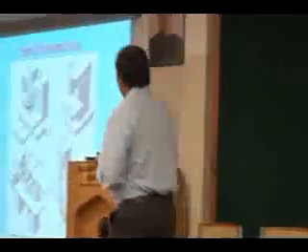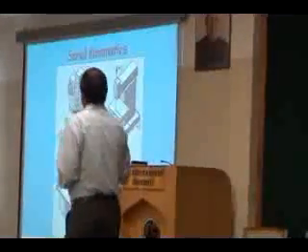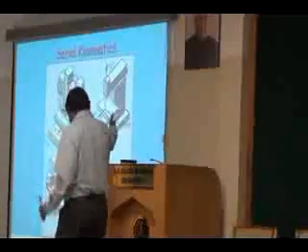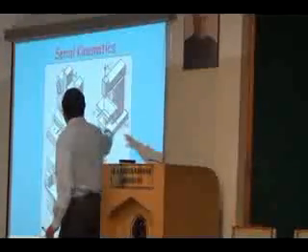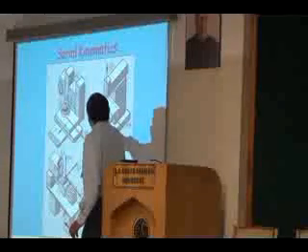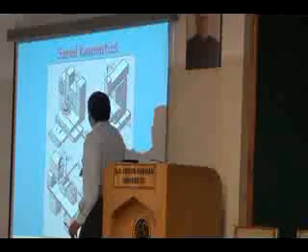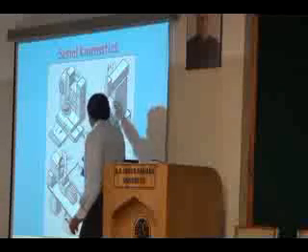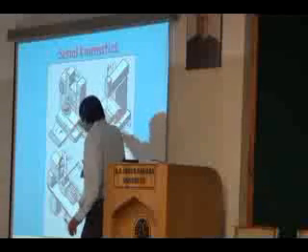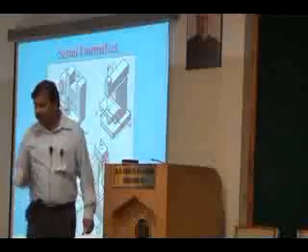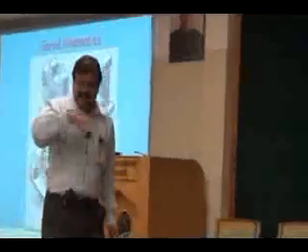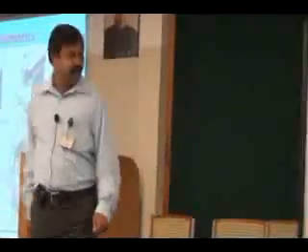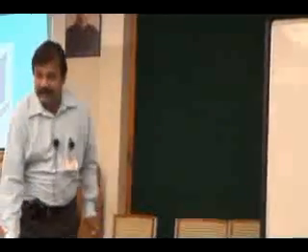Is it okay? You go to the milling machine. If you see this machine, the base thing is the z-axis motion. On top of that you have the x-axis motion. On top of this I should have another arrangement which will provide the y-axis motion. The axis motions are connected in series.